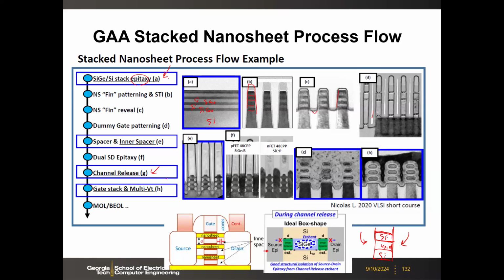And then you do this real gate stack regrow. Here you are going to regrow a gate stack surrounding the silicon. Okay. And then you get the metal gate in between. So finally, you get this kind of cross-sectional view. Here the source and drain is in and out of the plane. So we are looking at the cross-section, the nanosheet, right? We are looking into this nanosheet from this side view.